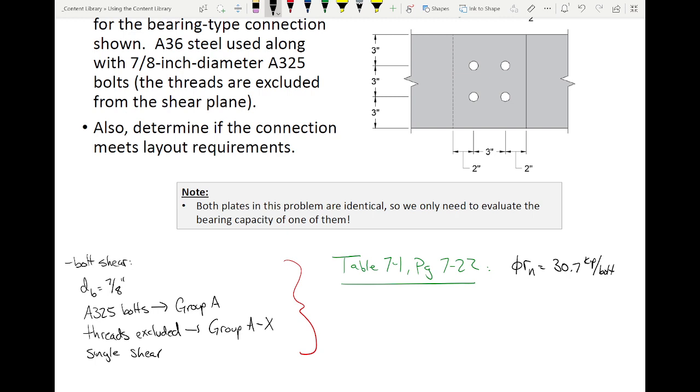Are there any questions? I'm guessing the higher one's just like a range too, so we use the lower for... no, hold on. Oh yeah, okay, I remember. That's single shear versus double shear. So it's double because there's two planes. If, for instance, you ever had a bolt that was in triple shear, just take the first one, multiply it by 3.